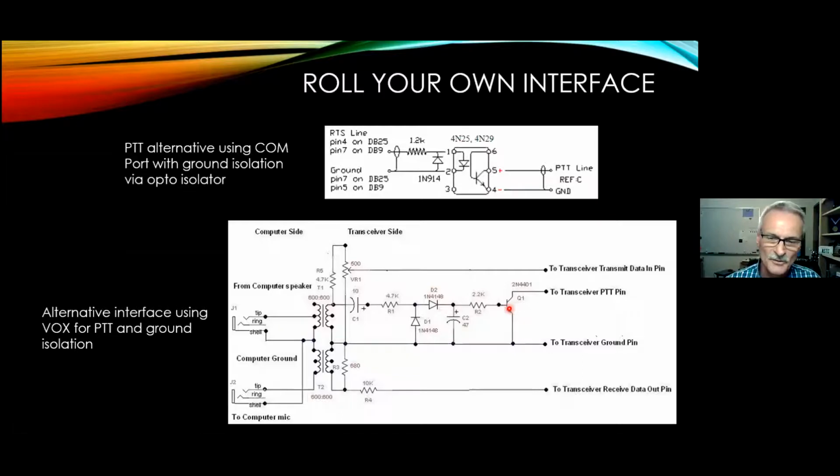When the sound goes away, this capacitor will bleed off, and we'll drop the push-to-talk connection. So getting this capacitor right is going to be critical. You don't want it to take too long to start transmitting, and you also don't want the radio to stay in transmit once we've done sending audio. So getting the right size capacitor here will make a big difference.